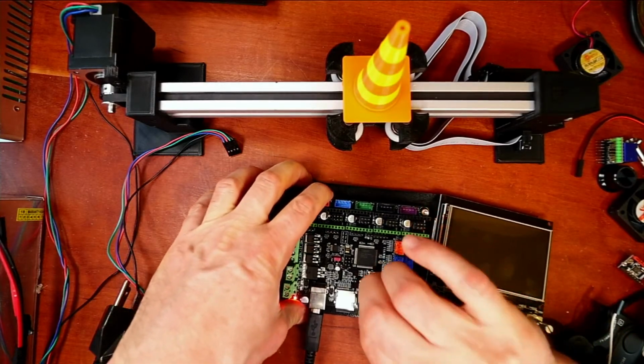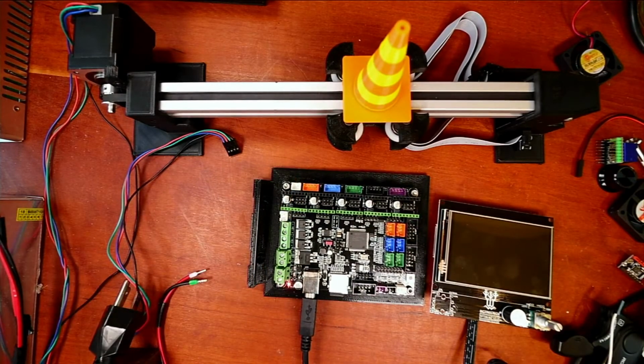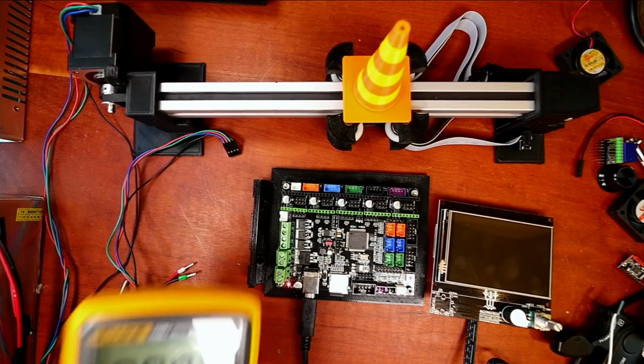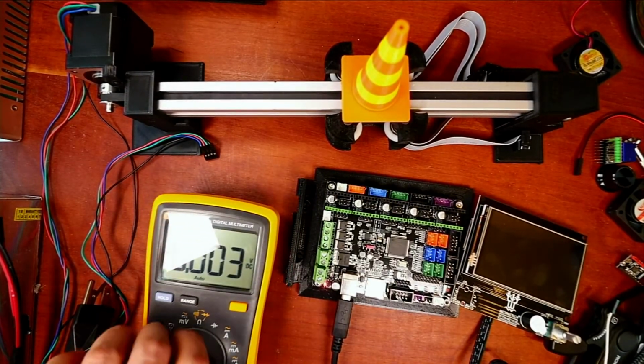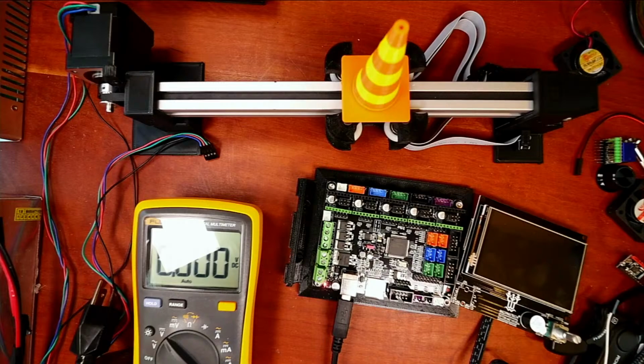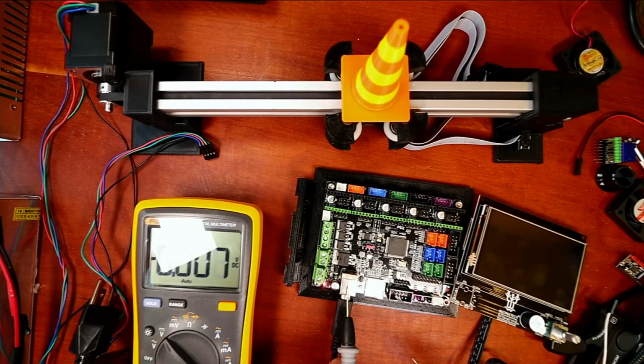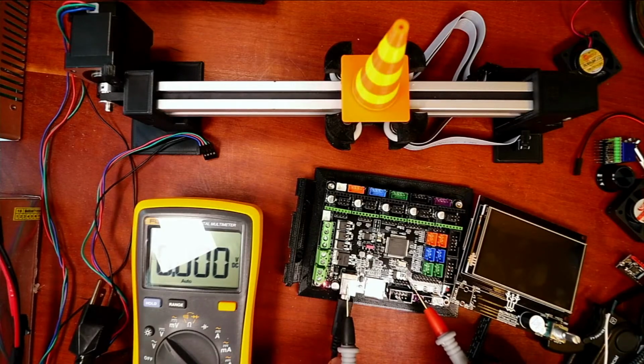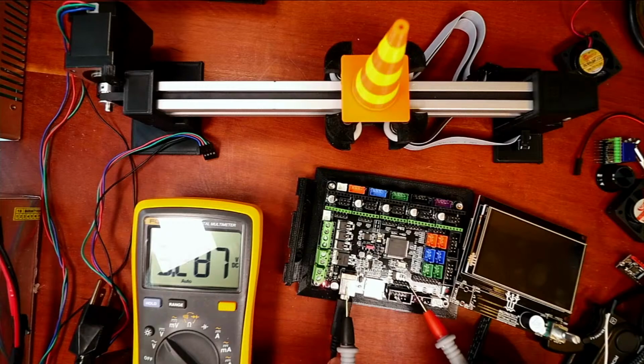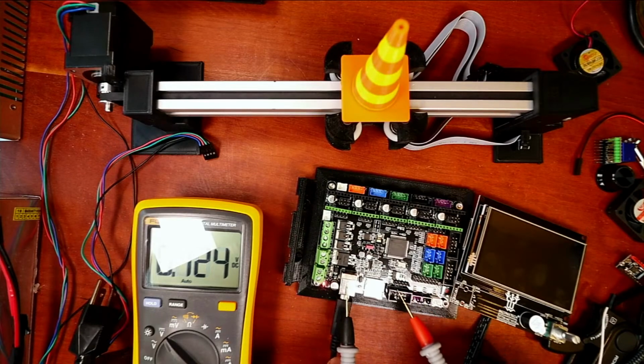I'm going to disconnect this. I'm going to take out the multimeter. Hopefully I'll put it where you can see it this time. So here's the multimeter. Actually, I got to power cycle it again. And I'm just going to measure pins. I'm going to go to a ground plane, and then touch a pin. Normally you could pull these off the board. That says 3 volts. Try over here. That says 4.81 volts.